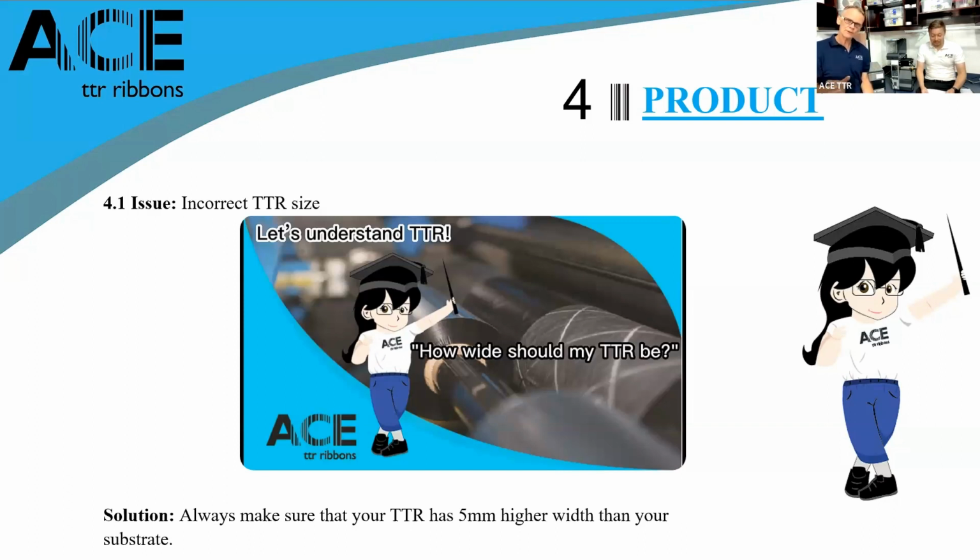And the best way of doing that is that we make sure that the TTR is larger, wider than the substrate, particularly with substrates that are harsh or coarse. We have materials like polyester satin that at a micro level are quite tough if you're going to get into contact with it. So very simply, the solution is, order your TTR no less than 5 millimeters wider than the substrate. And this will protect the print head from coming into contact with the substrate.